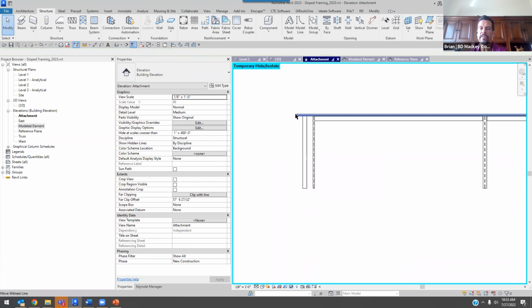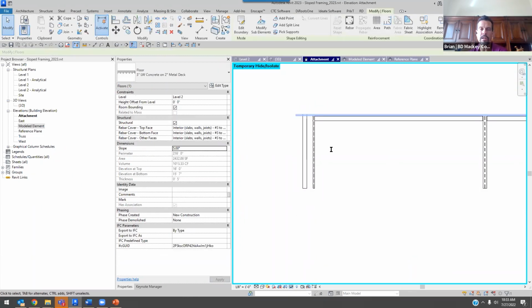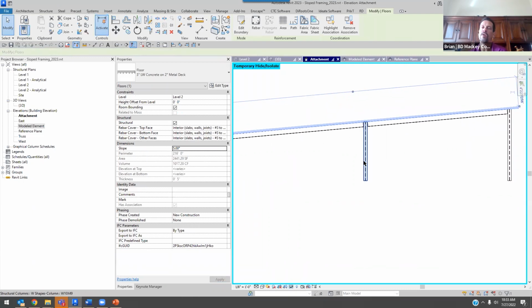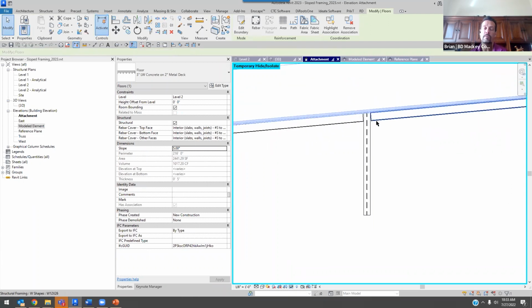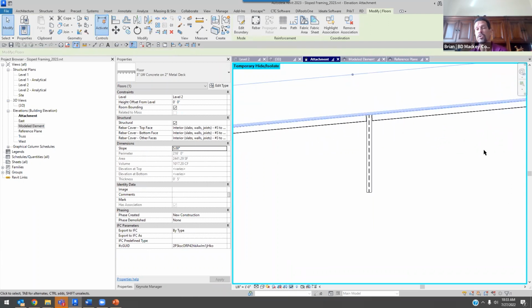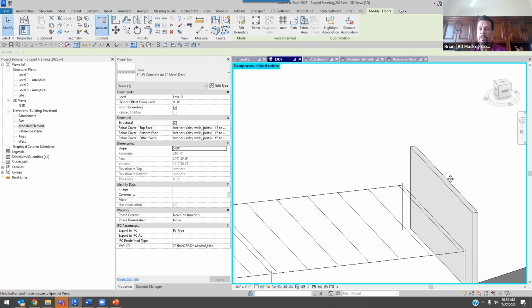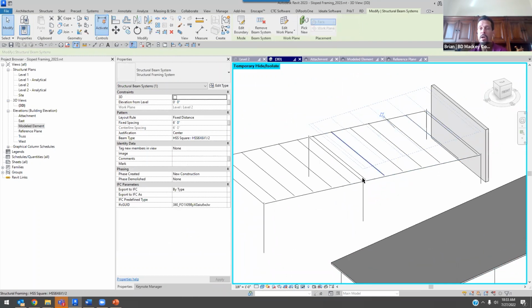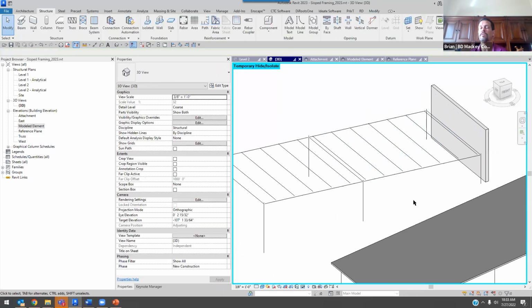Now what's beautiful is if I select this roof and be like, oh, that needed to be a 5-degree pitch, all of the columns go along for the ride. The beams are associated to the columns, they went along for the ride. The beam systems are associated to the beams, they went along for the ride. So as I start to look at this and play with this, you can see my beam system is still saying, hey, theoretically, my definition is up here, but this beam system is associated to the beams. It all goes along for the ride.